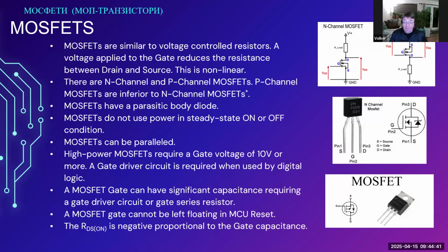If you make a software error, a firmware error, the watchdog circuit kicks in and forces a reset of the microcontroller. During the reset, all pins on the microcontroller go to high impedance mode. And now you have a load switch, some kind of device that is turning on a motor that is connected to a MOSFET. And now the MOSFET gate floats up. The MOSFET turns on. The motor turns on and might harm somebody. So that is a major problem.